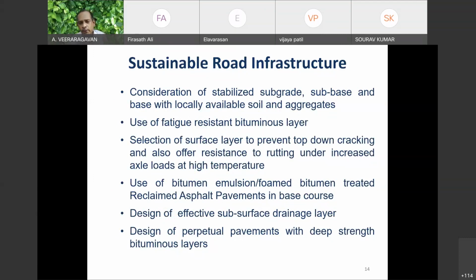So one is going by the book. You take the book, code or any specification, it tells the physical properties, mix properties, you design in the laboratory and you assume that this will be translated directly in the ground. There only we are failing. Many times what we do in theory, we will not be able to practice because of many issues of constructability.